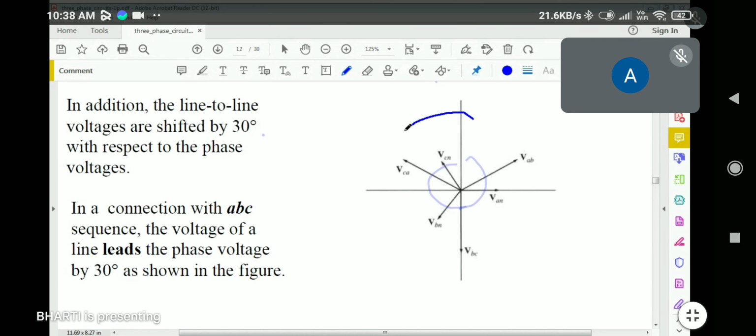तो ये फेजर आपने याद रखना हमेशा. You can draw this phasor also, in which you can see the difference in the angle between phase voltage and the line voltage, V phi and VL. Okay, that we can see here. There's a difference of 30 degree which is being maintained between every line and phase. You want to draw it?